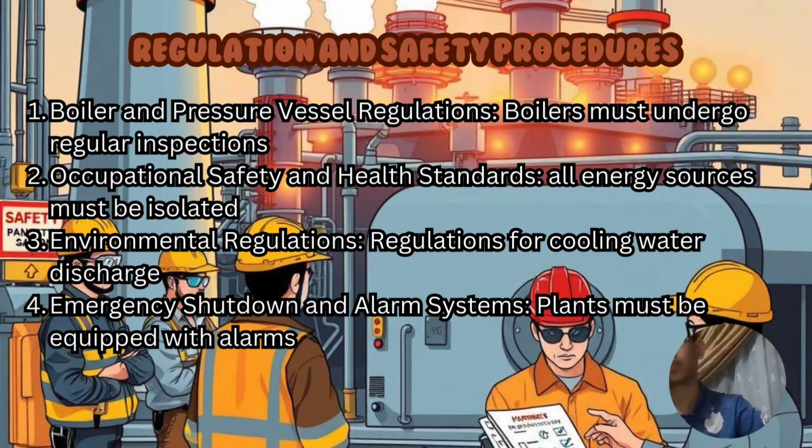And the second one is for the occupational safety and health standards. Regulatory bodies in the US, the Occupational Safety and Health Administration regulates safety procedures, while the Health and Safety Executive performs similar functions in the UK. Worker safety, regular training for workers on steam system operations, hazards identifications and emergency response. Personnel must wear proper personal protective equipment, which is PPE, such as heat resistant